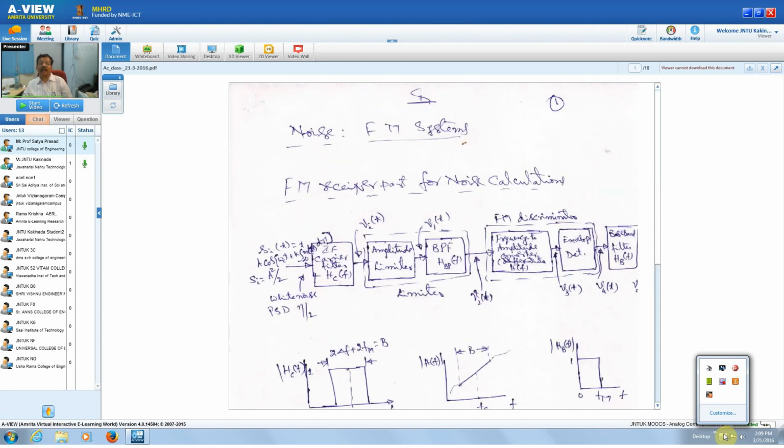and this has been given to our baseband filter. And this baseband filter, because we have a tuned circuit, once again gives back a sinusoidal output from this square wave. So the input signal for this filter is the amplitude limiter output, Va of t, and that has been converted into V1 of t. The output of this band pass filter we denote as V2 of t. So this has the required frequency variations, or the modulation.